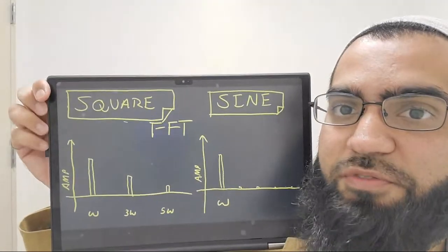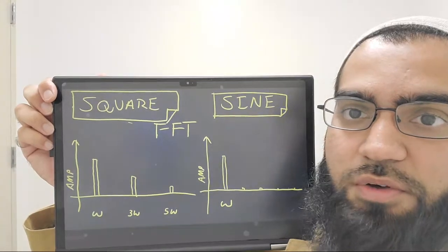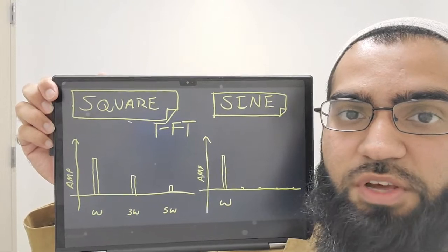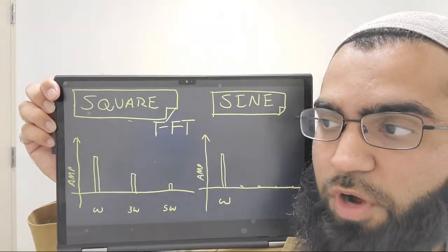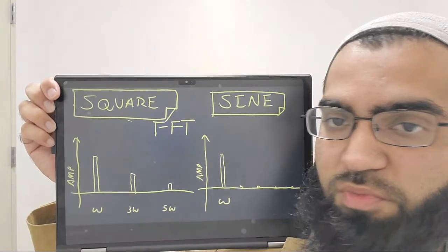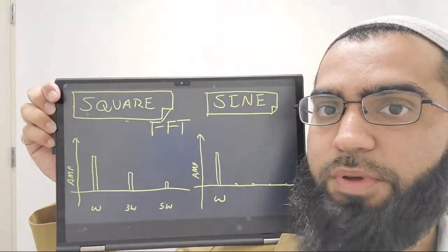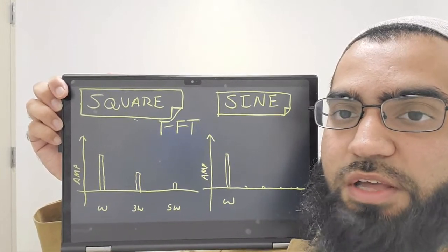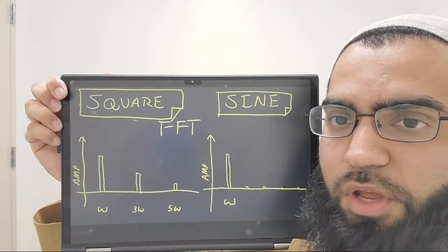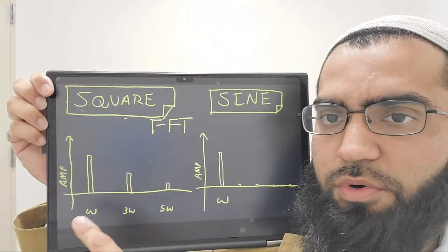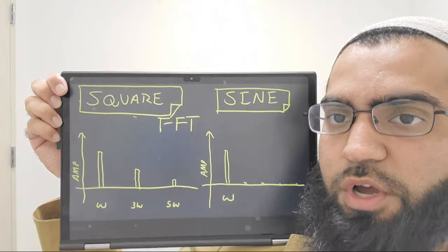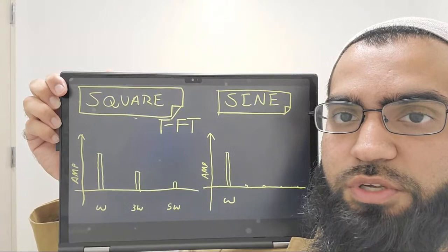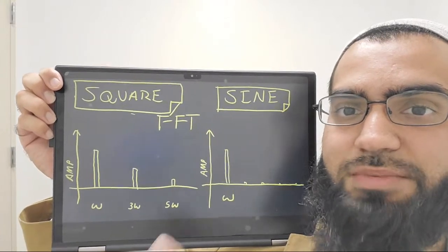So the biggest difference between just looking at the waves themselves is the spectral content, which you can see using an FFT, for example. Plug into your oscilloscope a square wave from a function generator, or even from the calibration pins that produce a 1 kilohertz wave, and then you implement the FFT and see the spectrum. I believe this is correct for a square wave: it's odd harmonics.